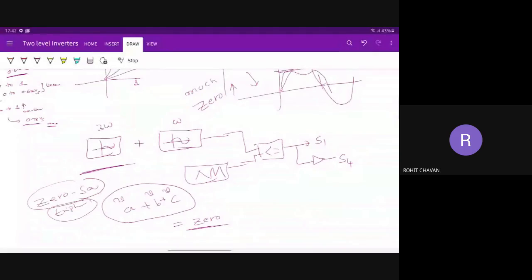Power system you might have studied: positive sequence, negative sequence, and zero sequence. During fault analysis, they are related to fundamental frequency components only. Each phase's unbalanced currents or voltages we divide into sequence components. Here zero sequence and triplet both are the same. Any questions on this?